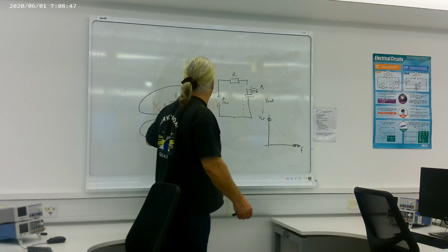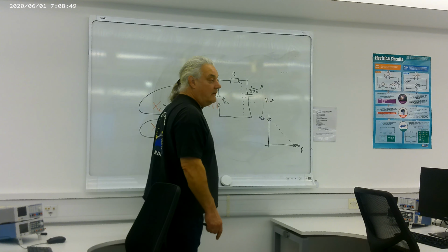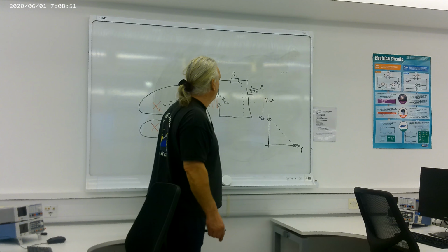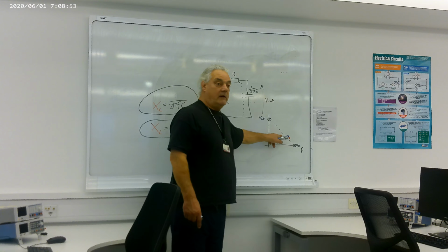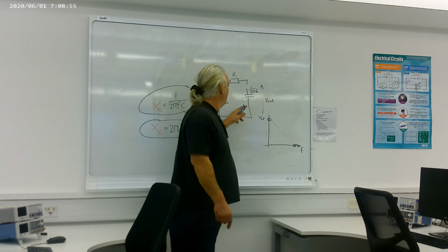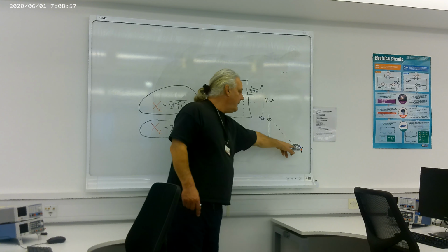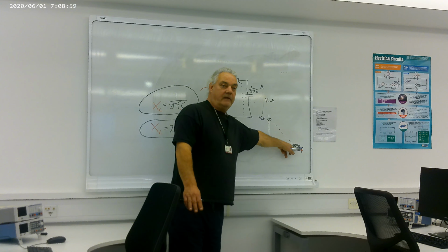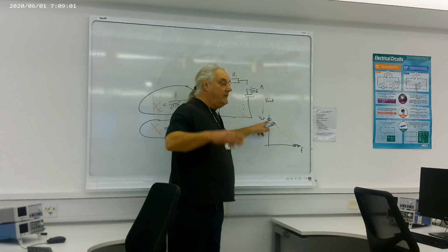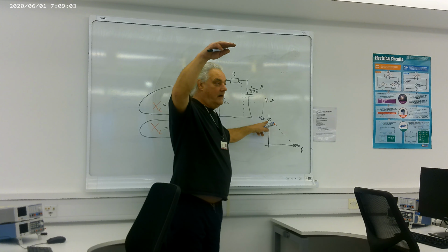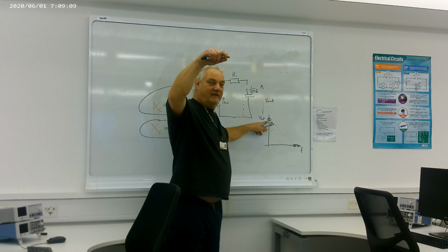So we haven't plugged any numbers in, we're just using algebraic equations. And yet we can derive this, which tells us that in this circuit at high frequencies, the output's next to nothing, and at low frequencies, the amplitude is very high. Anyone know what that's called?